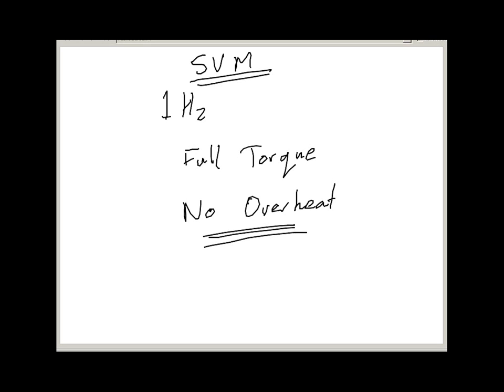What these people did, the people that were in the week before last, sorry, is they went back to their site and they looked at the VSD documentation, and they found the manufacturer's equivalent of space vector modulation. I think it was called voltage modulation or something along those lines. They enabled voltage modulation, and immediately the temperature of all of the motors dropped 20% of what it was running before. So it does work.